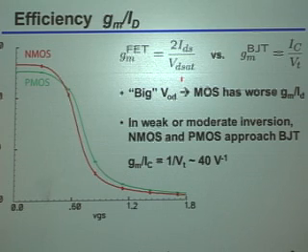So just to be clear, what do people mean by that? What is it that's better about a bipolar versus a CMOS transistor? Yeah, for the same bias current, you get a higher GM, right? Because basically, you get that 1 over thermal voltage or that 1 over 25 millivolts. No matter what the bias current is, immediately you get that as the transconductance efficiency, right?